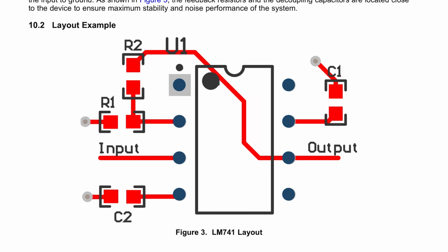In this particular case, I just wanted to bring it to your attention. The rectangle with a semicircular cut is actually the chip package of this amplifier, and that black dot represents pin number 1. That uniquely identifies pin number 1, so that you don't flip it around and make a mistake.